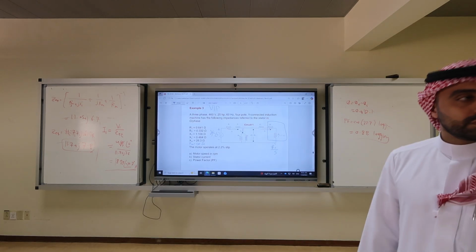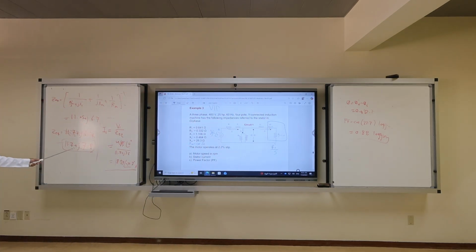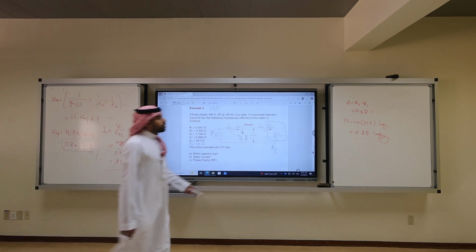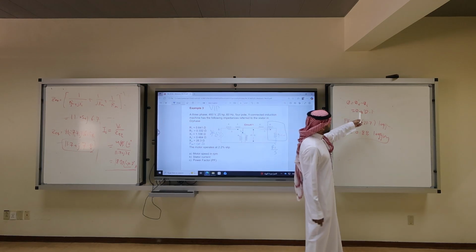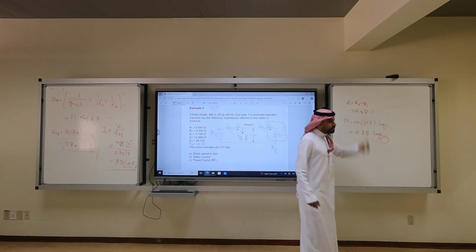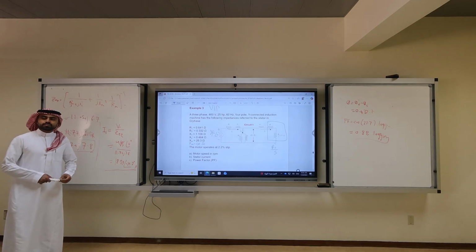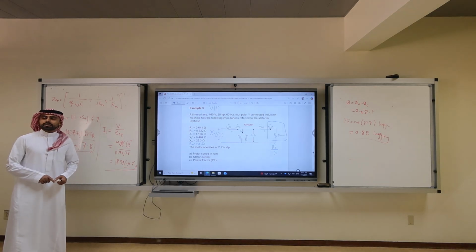Theta is plus tan inverse of 7.8 over 11.7. So we always look at the Z equivalent. Yes, you have to know your load. You can get the cosine from the angle here. If the angle theta is positive, you know it's lagging. This theta is positive, which is plus tan inverse of this. All induction machines should have lag.